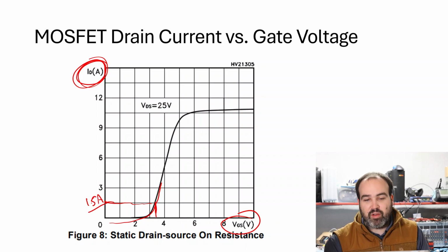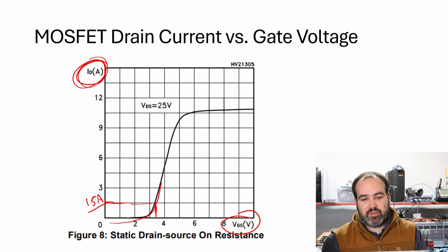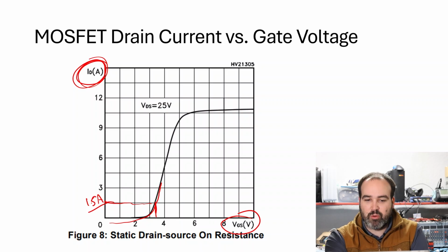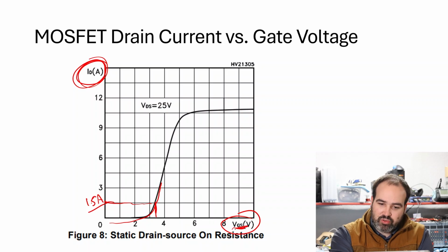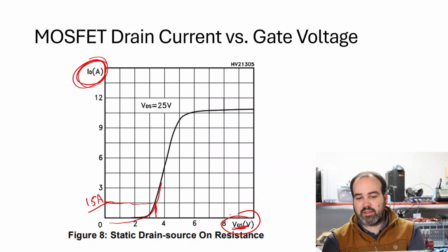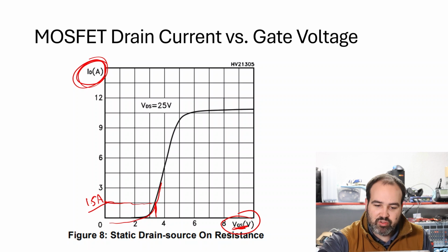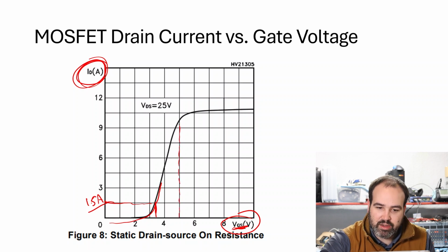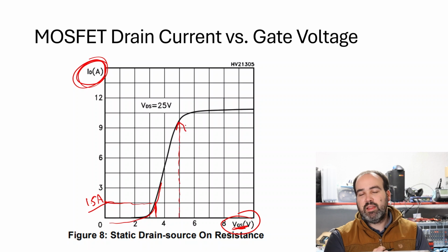If we try to put through that current, it's really heating up the MOSFET. Right, so this part would not be good for a logic level application where all I can do is drive the gate to source at 3.3 volts. If I could drive it at 5 volts, right, that's looking way better. So this is probably a 5 volt sort of logic level part.